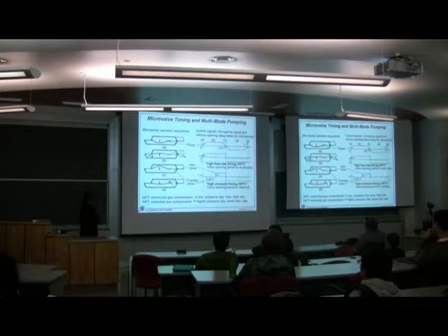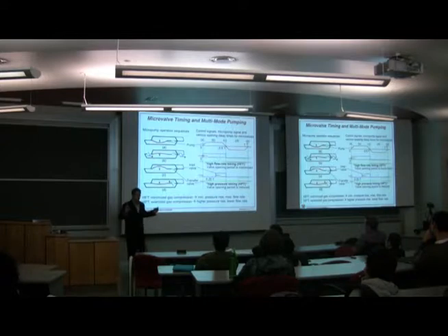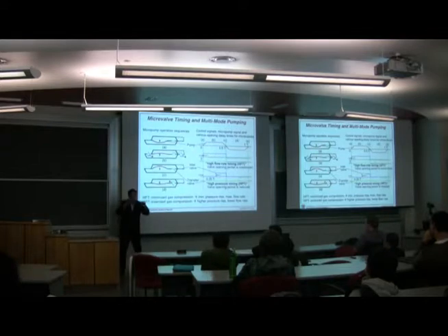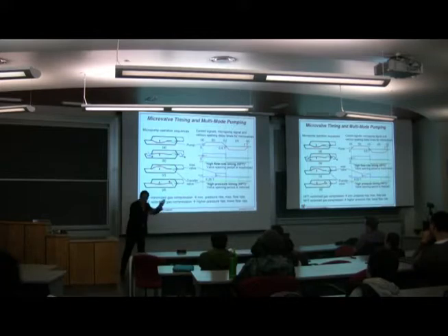The key point is now the control aspect. So you can generate airflow, but can you control it well? Indeed, yes. Whenever these membranes move up and down, there are certain timings at which you can open and close, right? If you open late, then the air will be compressed longer, which means the pressure generation will be larger. But instead, the transition time from one chamber to the next will be shorter because it's open less. In that case, we can generate higher pressure and lower flow rate.